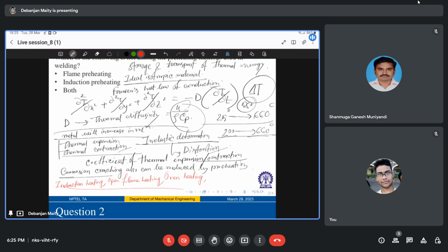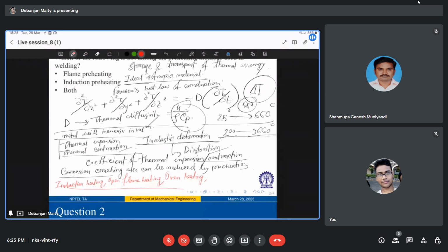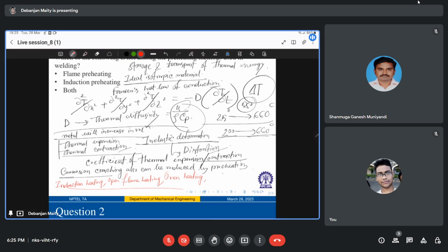It creates a magnetic field that generates eddy current within the base metal, and you are heating it internally through these induction accessories, such as cables, or blankets, or some coil of wire like this, and you are basically applying some kind of magnetic field to generate this eddy current.